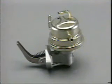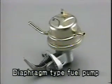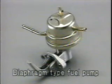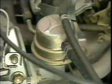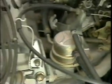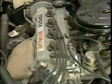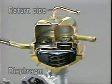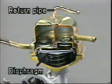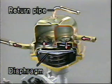The fuel pump draws out fuel from the fuel tank and sends it under pressure to the carburetor. The diaphragm-type fuel pump shown here is the most common type of fuel pump used with carburetors. The diaphragm-type fuel pump of the 4AF engine is installed on the engine block and is driven by a cam on the engine's camshaft. The fuel pump has a diaphragm in it and a pair of valves which act in the opposite direction from each other. These valves are actuated by the reciprocating movement of the diaphragm and feed the fuel to the carburetor.